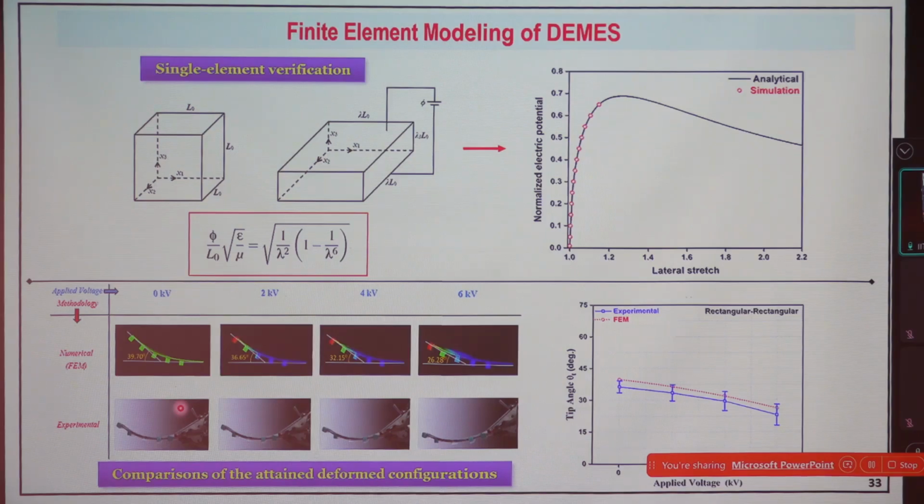For the finite element, we developed a single element. Then on the deformed configuration, on this particular active area, you define multiple elements. So we have the mesh with this 8 noded continuum brick element on the active area. Then you apply the potential difference. So on that active area, basically, you are applying the voltage, and it will try to go back.